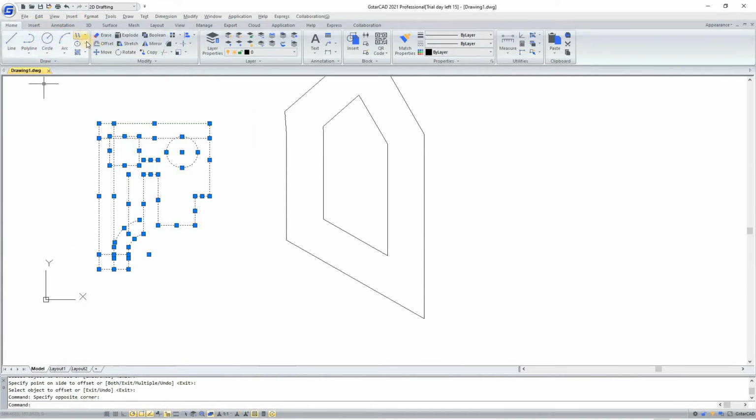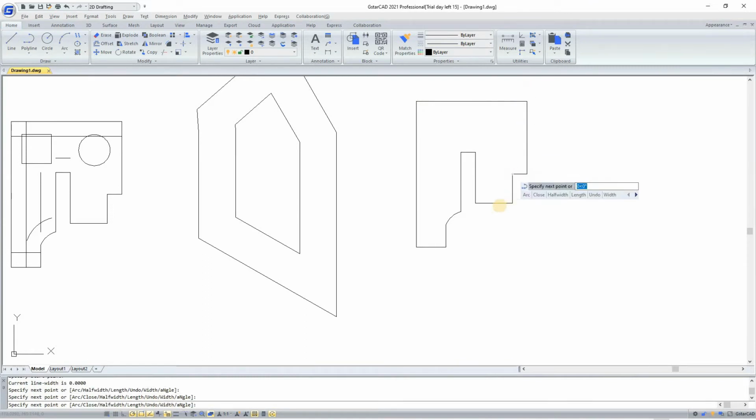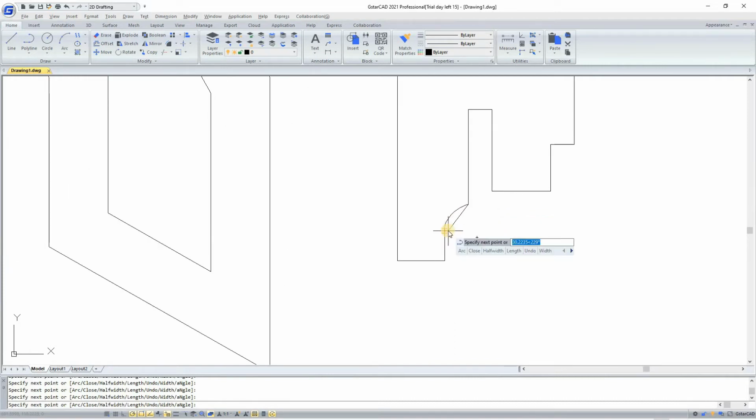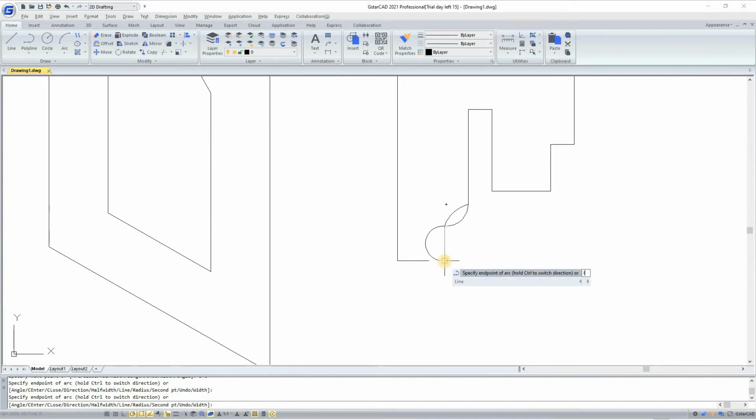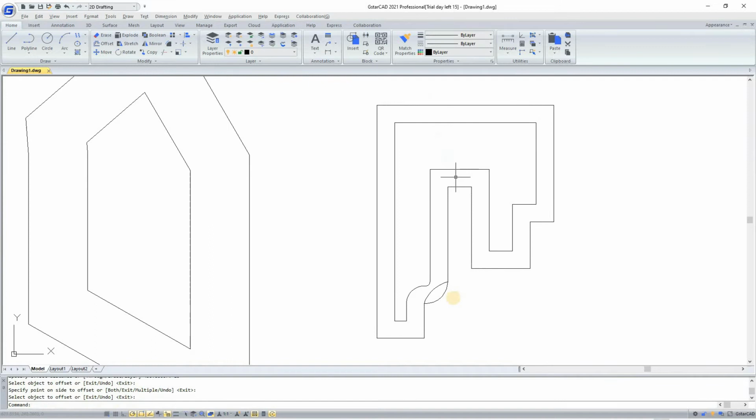If we are going to copy this, we're going to delete this in a particular way, and we're going to draw a polyline based on this. And if we choose offset, say 15, it offsets, and look at this, you have a nice road.